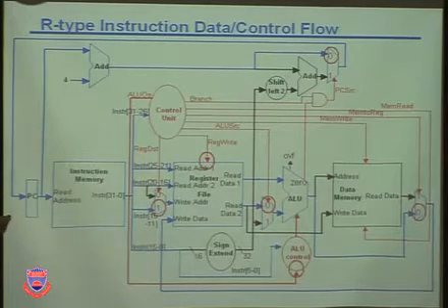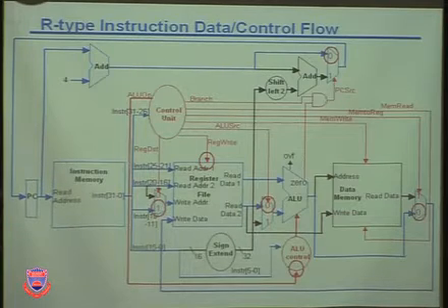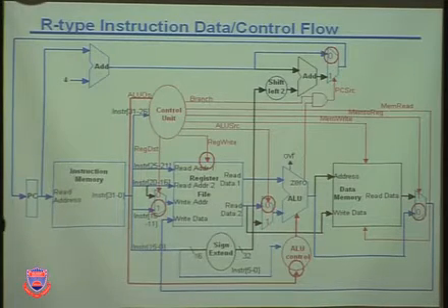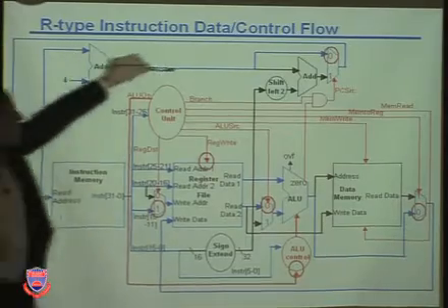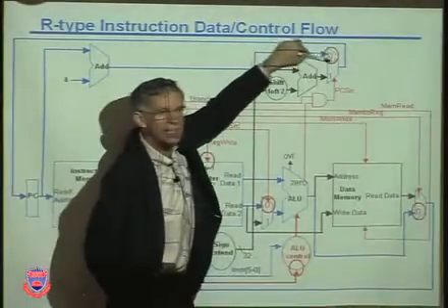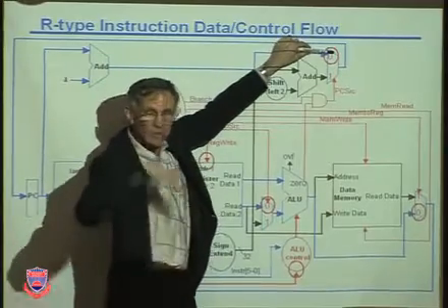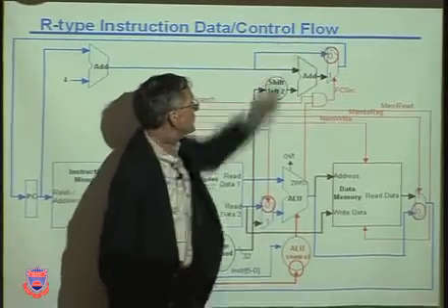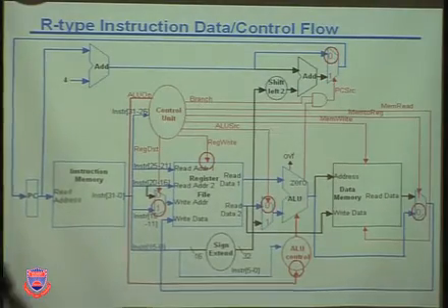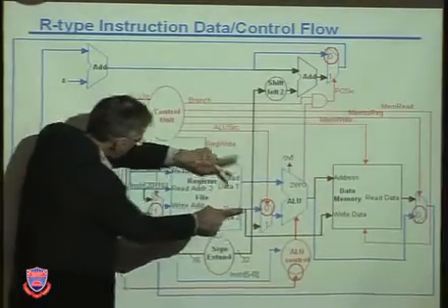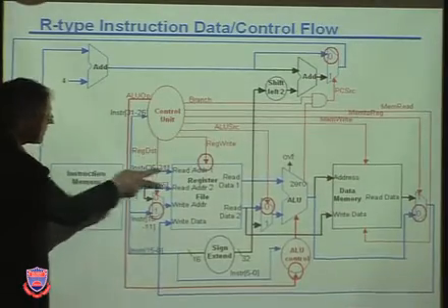For an ALU operation, an R-type operation, we're just going to go to the next sequential address. We're not going to branch off to somewhere else. So that means the current value of PC plus 4 gets selected at the MUX, and that's what's going to be sent back around. That makes sense. We're going to sequentially increment, so we circle that one. It also means that we're going to fetch 2 register operands using the RS and RT values coming from the instruction. So here they go.